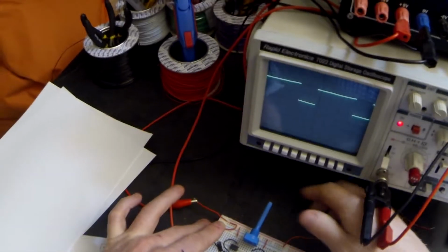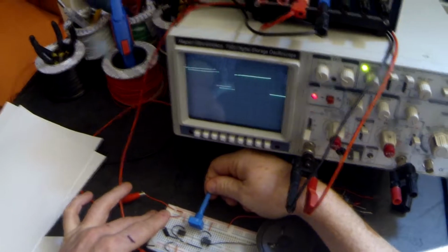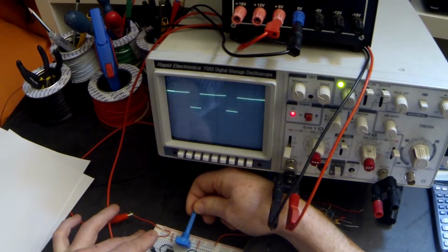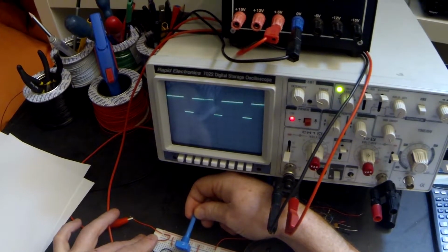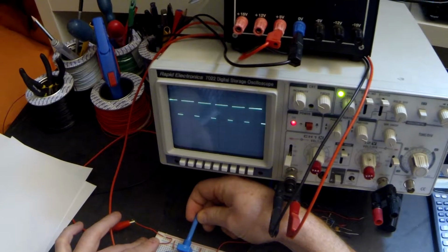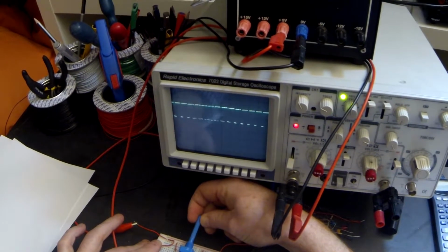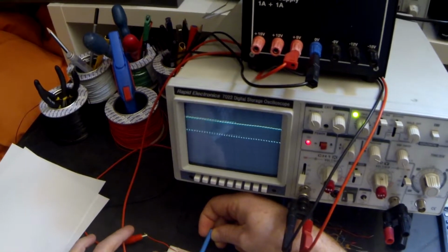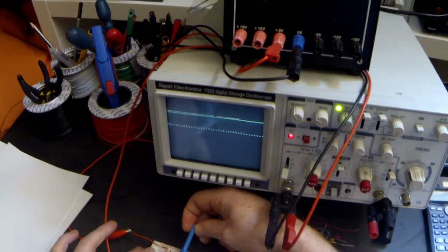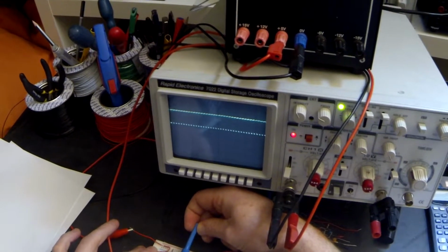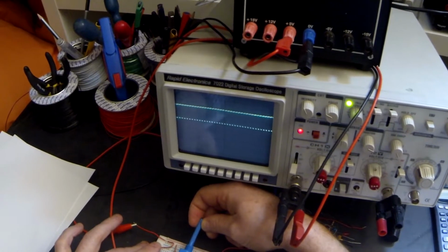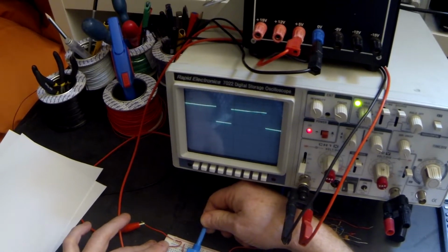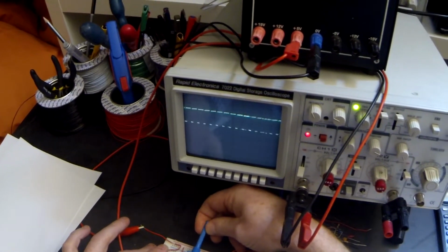Now, one other thing, we said there was a variable resistor. As I change that variable resistor, you can see the waveform get a lot closer together. So the time period has decreased and you can fit a lot more of those waveforms in on the time base that we're currently on. And down again. So you can have a little play with the frequency.